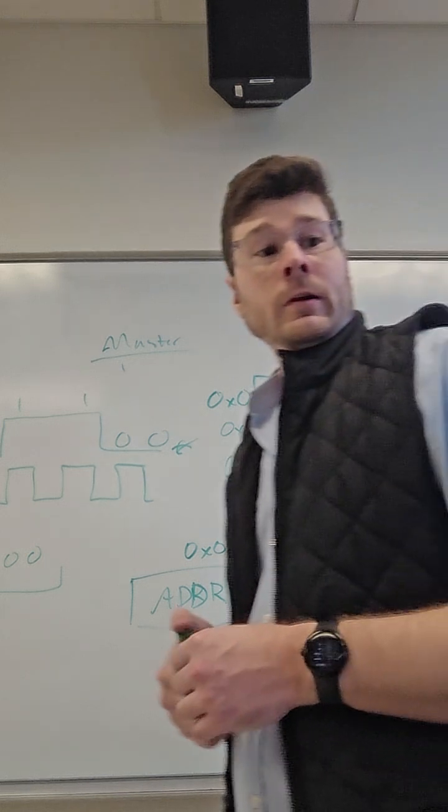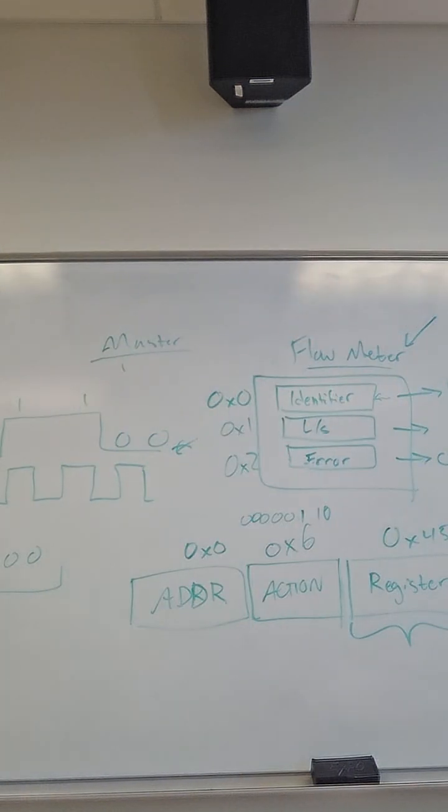So, this is what I was talking about for why PLC to PLC communication can be so cool, is because we can control so many different devices, and we can have such control over system architecture, right? Depending on the layout of our factory, for example, it might make sense for this one process that has a whole bunch of different actuators and sensors on it, maybe a closed loop feedback system, that all of that should be going to just one controller.